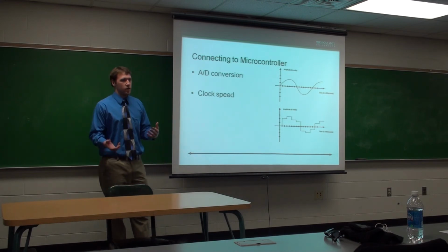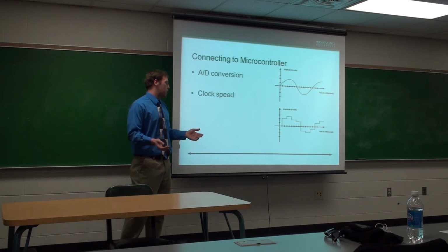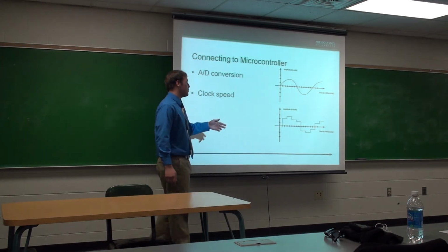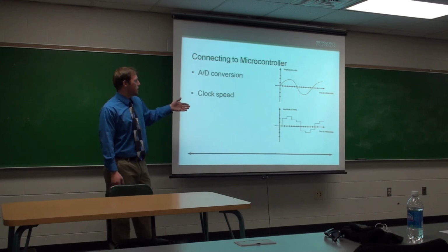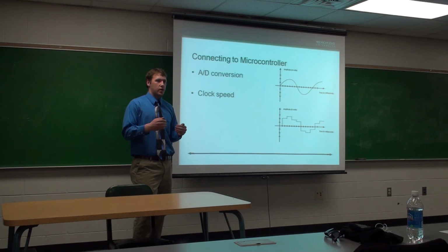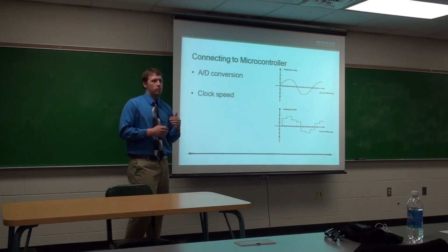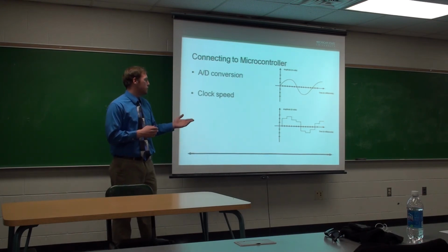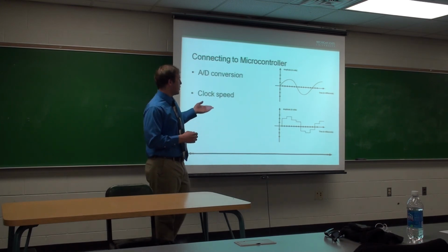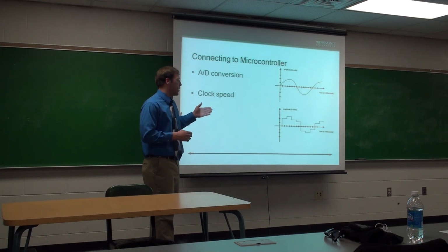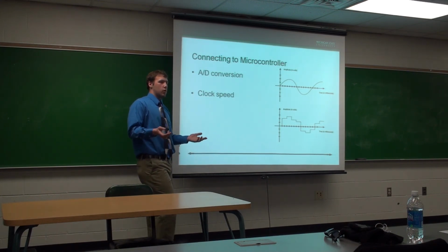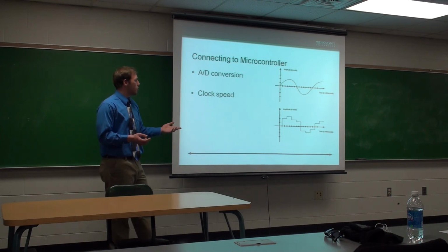It's the most robust rate we've come up with, so it works very well, and it allows for very good data recovery when we're trying to digitize a signal. Another reason why we try to digitize signals is because the microcontroller reads these signals, and the very well-defined quantization levels help it make its decisions when it comes to a feedback loop or that type of thing. And the last reason why we use digital signals is they tend to travel very well through the hardware, and it's also picked up really well by the microcontroller when it comes through the hardware.